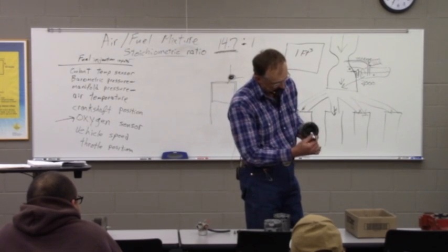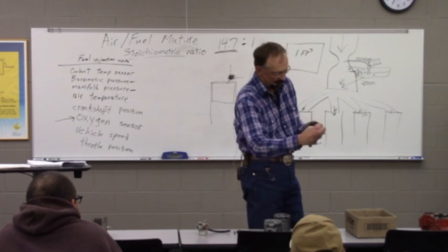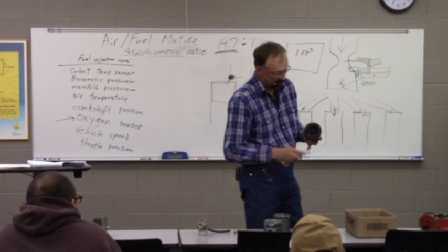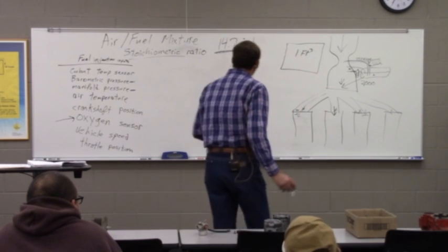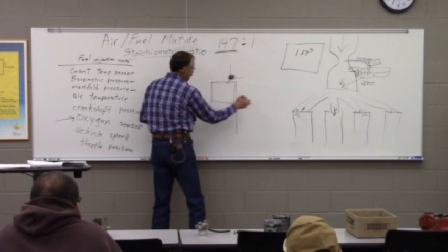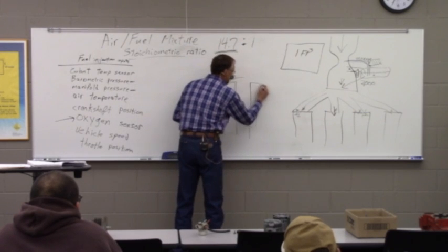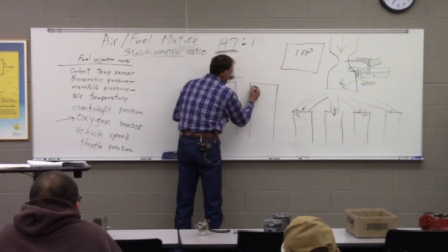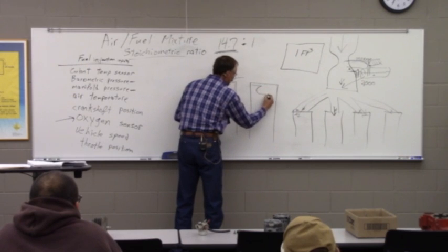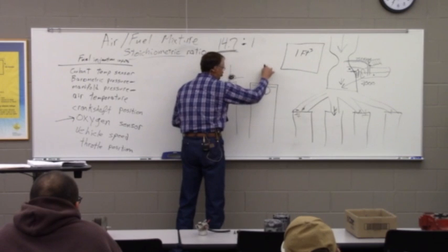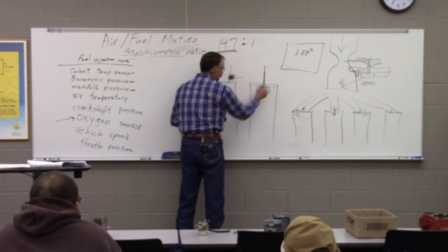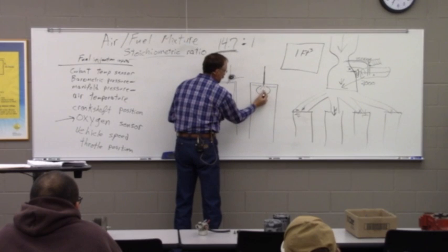So you can see the injector spraying here, and it sprays kind of a cone-shaped mist of fuel. If we take this piston, I'm going to draw another one over here. We've got a chamber like this, and all of these I've ever worked with actually have kind of a point there in the middle. We're going to spray our injection right here, and it'll come out like this, and it actually swirls like this.